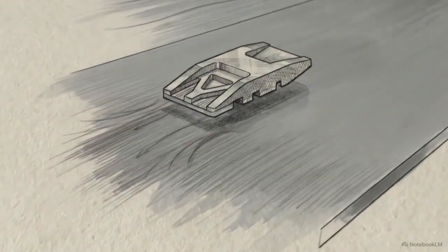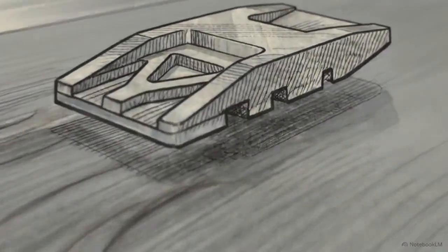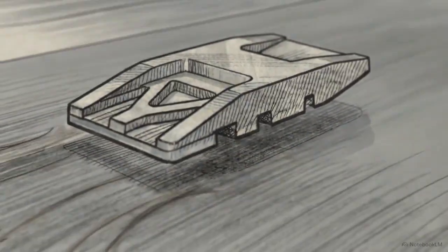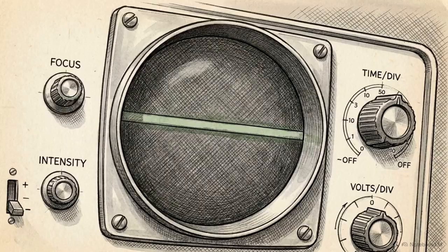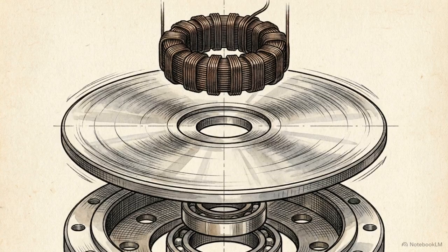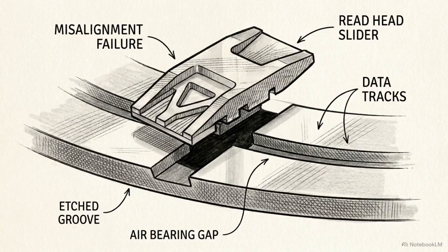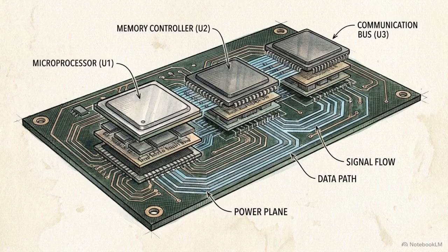Relying strictly on the timing of these shifts creates a severe logical vulnerability. If the computer saves a long string of identical zeros, the magnetic field remains static, and the read head receives no timing signals at all. Without regular polarity shifts, the electronics recapture the data using a phase-locked loop. During a long sequence of identical bits, that loop loses synchronization, making it impossible to determine where one bit ends and the next begins. Drive engineers solved this timing drift by employing an algorithm called modified frequency modulation, or MFM.